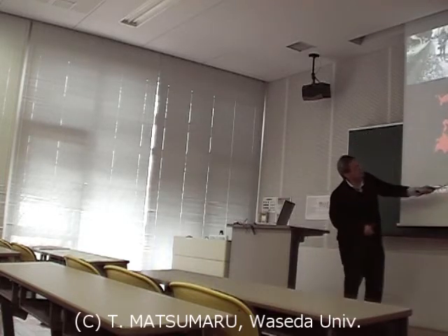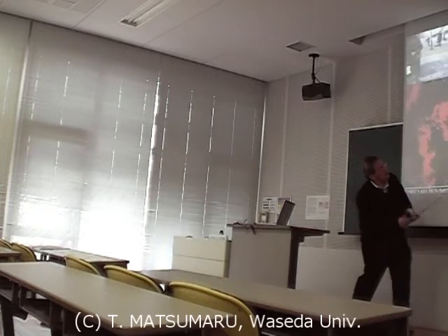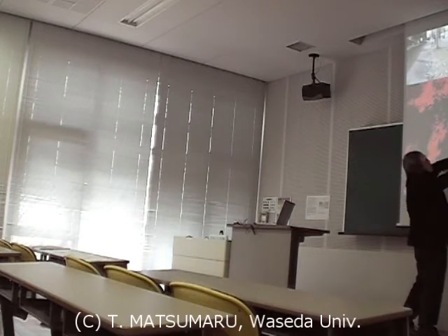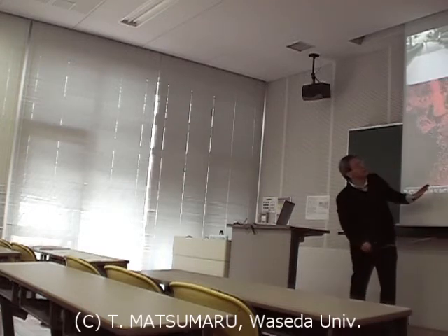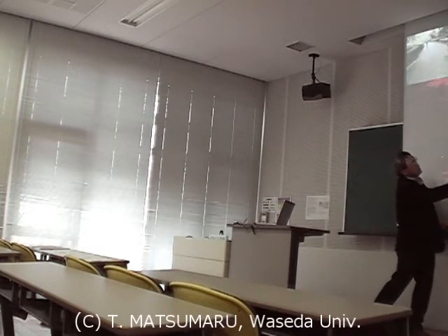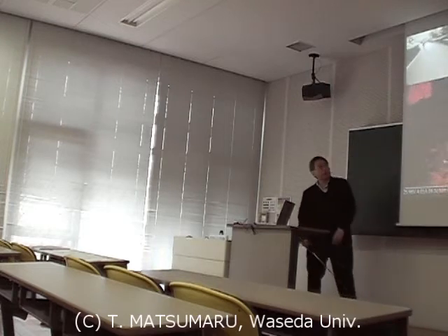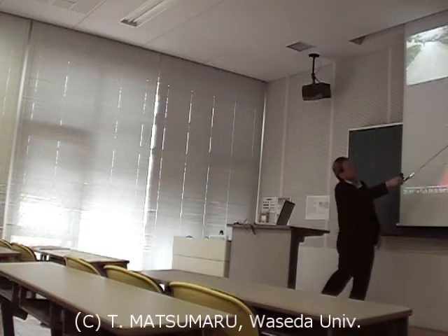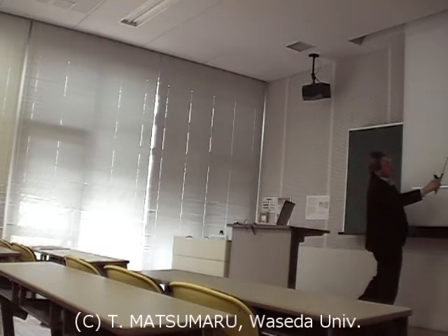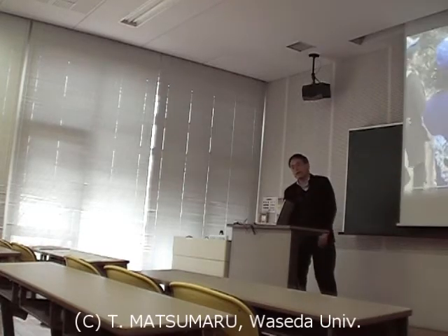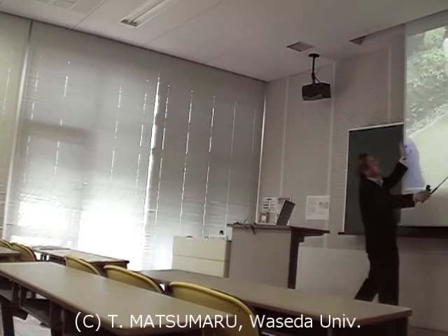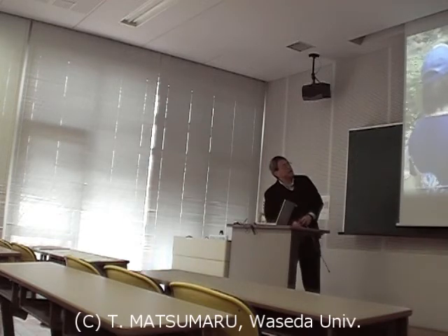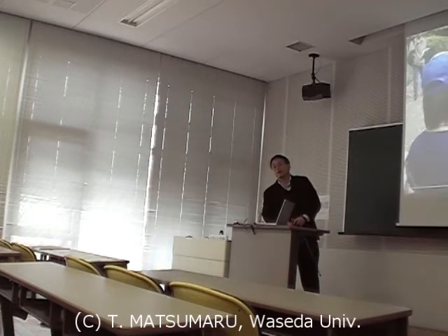Some parts are preliminarily prepared, and the scanning data is also matched to this preliminarily prepared three-dimensional map, and then the position is modified while moving. This green position is maybe the real-time scanning data matched with the preliminarily prepared environmental map, and then correcting the position.